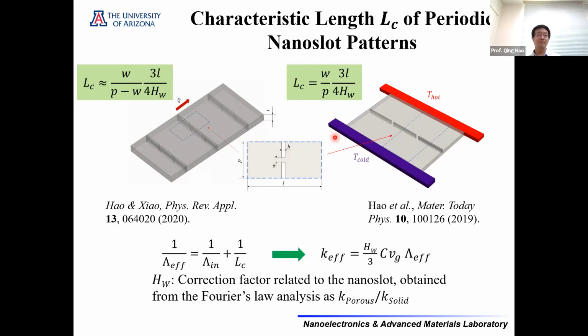Of course, if you think about the ultra-fine silicon thin films, or if you think about 2D materials, you are not restricted by this aspect ratio, right? Then in that case, for graphene, you can actually pattern the smallest size given by electron beam lithography, or you can directly use electrons to drill holes on graphene. That could be the smallest size you can achieve.